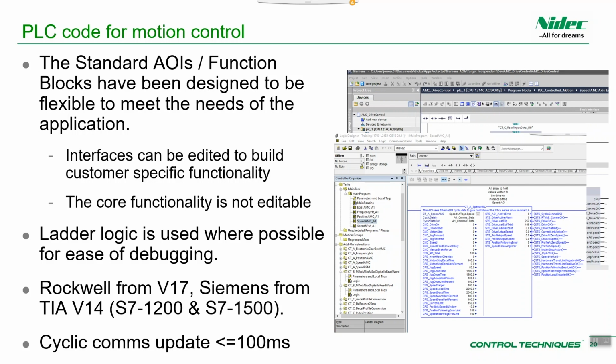Ladder logic is used wherever possible, just to meet the general customer need, really, and to make it easier to debug. Rockwell PLCs are supported from version 17 of the Rockwell firmware, and Siemens from TIA Portal version 14, specifically S7-1200s and S7-1500s.